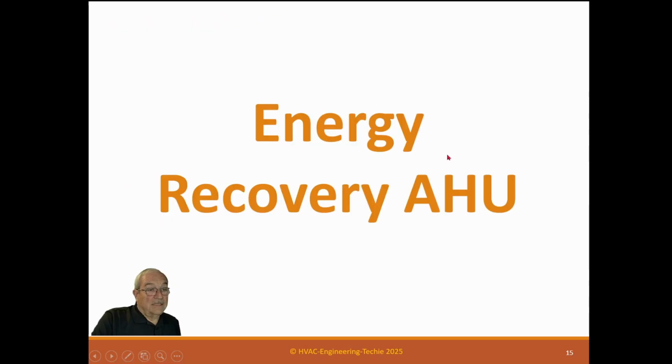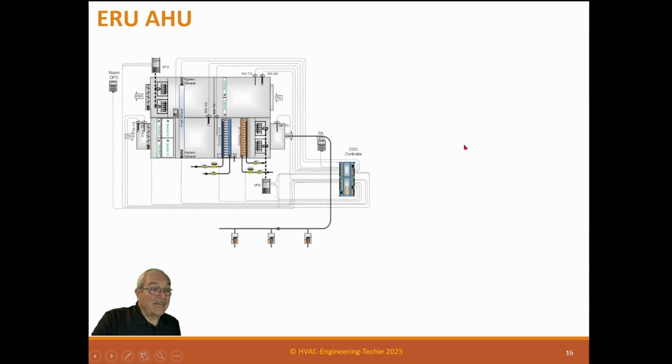All right, so an energy recovery air handling unit is exactly like a DOAS unit, but it's designed to be able to handle a large makeup air load. So basically this could be a system that has several large air handlers, say like auditoriums or something, that have a great deal of exhaust because they have a very high outside air load, very high ventilation load. And they will use these units either just for a single, very large zone, or for DOAS type units, other air handling units.